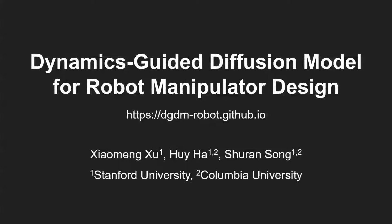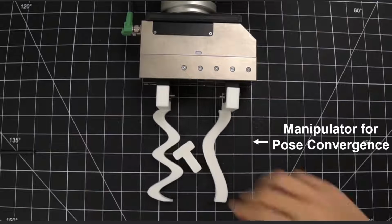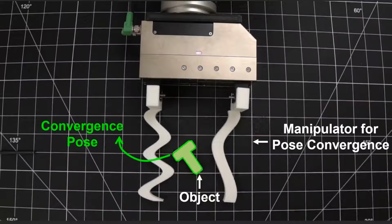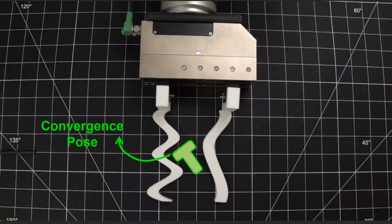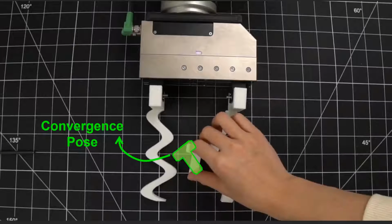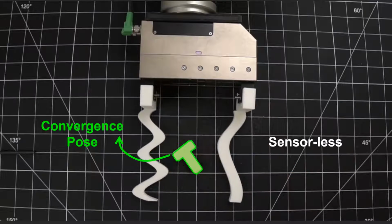We present Dynamics-Guided Diffusion Model for Robot Manipulator Design. This is a robot manipulator designed for post-convergence of this target T object. It means no matter how you put down the T, the manipulator is always able to align the T to the same pose after a few squeezing actions without sensors.